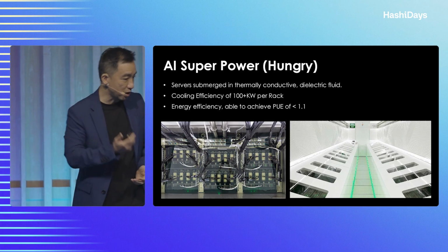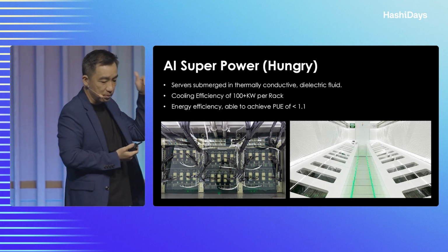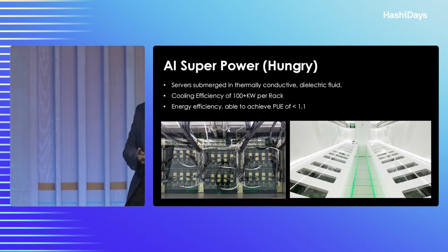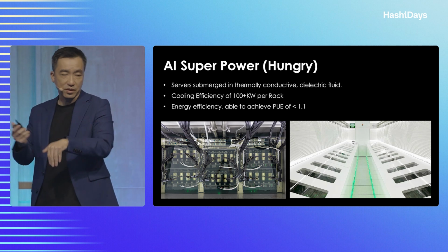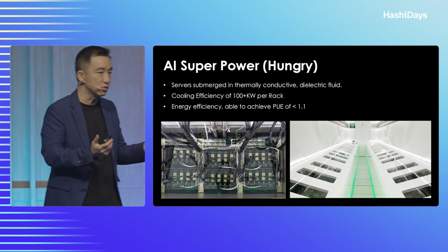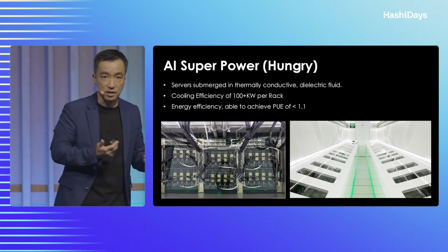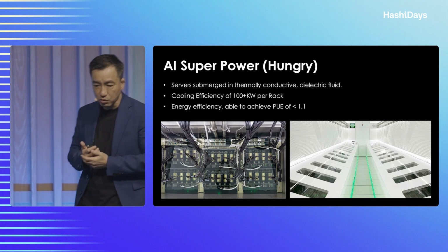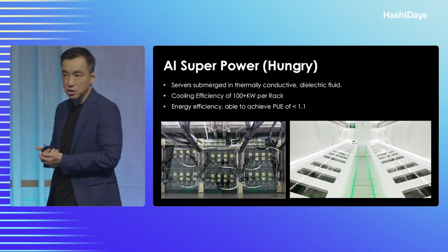And the next innovation we're adopting today is what we call immersion cooling. We dip the GPU into dielectric fluid, so it's non-conductive. You cool the GPU as it dips into oil, that's the way to look at it. The advantage of that technology is there's no fan, there's no mechanical vibration, which actually increases the lifespan of the GPU. So it gives us more than 100 kilowatt of cooling capacity, and it also increases energy efficiency.